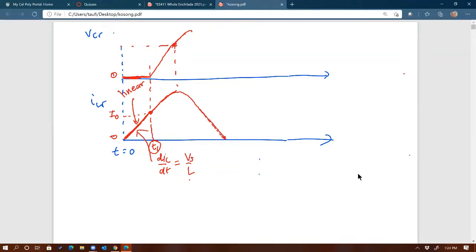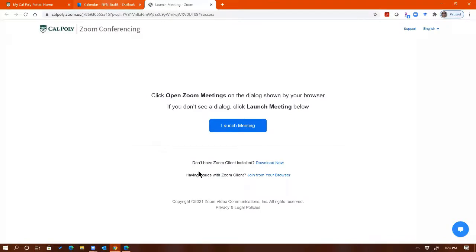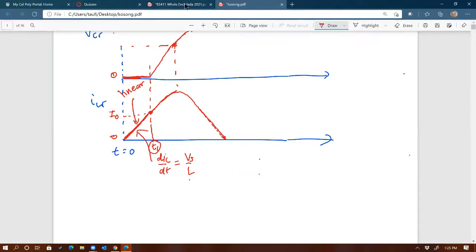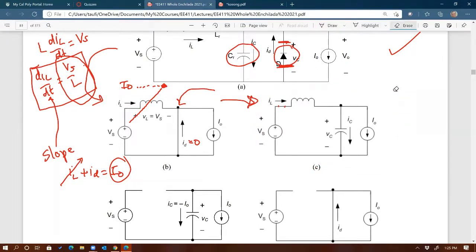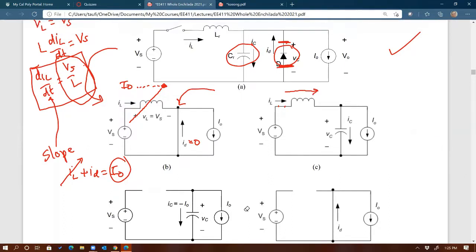So that's what we're aiming for in the second state. Inductor current is a sine wave, and so is the switch current. Capacitor voltage is also a sine wave. And we wait until the inductor current goes to 0, and when it reaches 0, then what happens? Imagine, I'm going to erase this, at this point the inductor current follows the sine wave, and at some point it crosses 0 and tries to go negative, just like a sine wave.